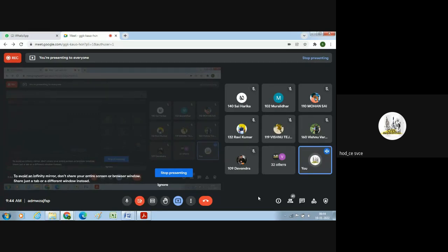The remaining readings in between the first and last are intermediate sights. There are two methods: the height of instrument method and the rise and fall method. Use any one method and calculate the RLs of each and every station. Finish. So we have calculated the RLs for each and every intersection point.